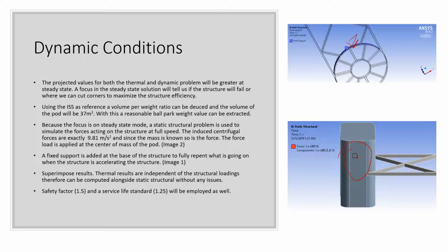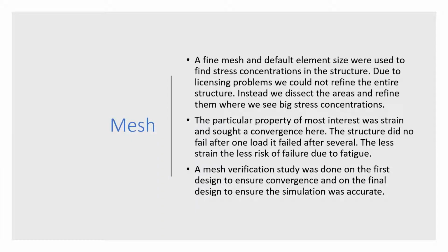Superimposed results. Thermal results are independent of the structure loading, therefore can be computed alongside the static structure without any issues. So a safety factor of 1.5 will be employed, and a service life standard of 1.25 will also be used. This was taken from the NASA technical standard book. This leads us to meshing.